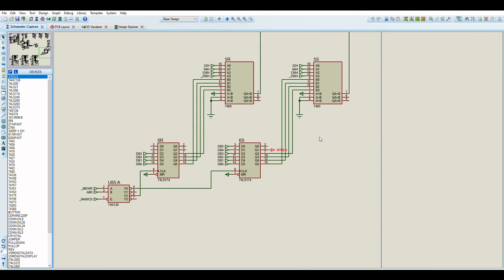And that meant that I could add extra sprites. So the standard BombJack hardware has 24 16 by 16 pixel sprites. Using the multiplexing technique, I can render 48, 64 sprites, no problem at all, by updating the sprite registers as the screen goes down.